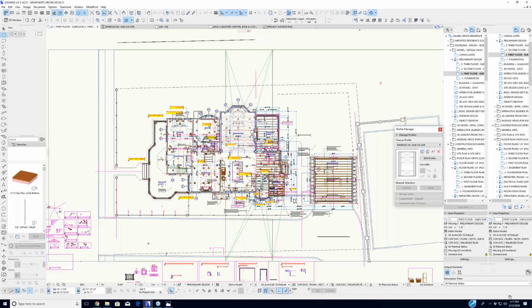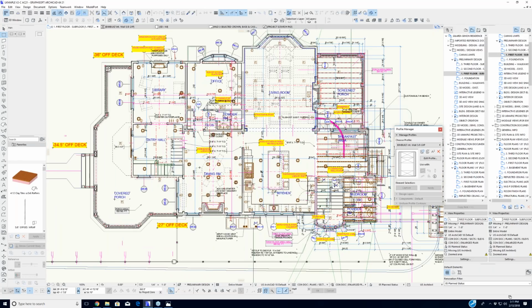I did that with a handheld laser, which is a very, very useful tool. They're about $100 to $200, depending on what version you use. They're made by Bosch, Milwaukee, Leica. It's a small handheld device. You can point it and shoot your measurements up to 1/16 of an inch accuracy, up to 150 feet. And that is how I documented this structure. I would measure all the windows, all the walls, ceiling heights. And believe me, the ceiling heights are different in every room, because some ceilings might have leaked and sagged, and they put another layer of drywall on the ceiling.